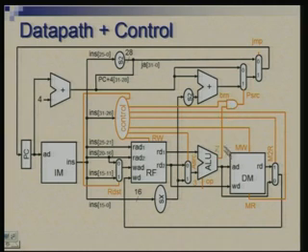Now, it will depend upon Z, we will get a 1 here or a 0 here. So, if the result of comparison was true, if the 2 registers were equal, this will be activated, this will be 1 and you will get a 1 here. So, this address will go as the next address of PC, next value of PC, and if the test failed, then this will be 0, you will have a 0 and PC plus 4 will continue, right.